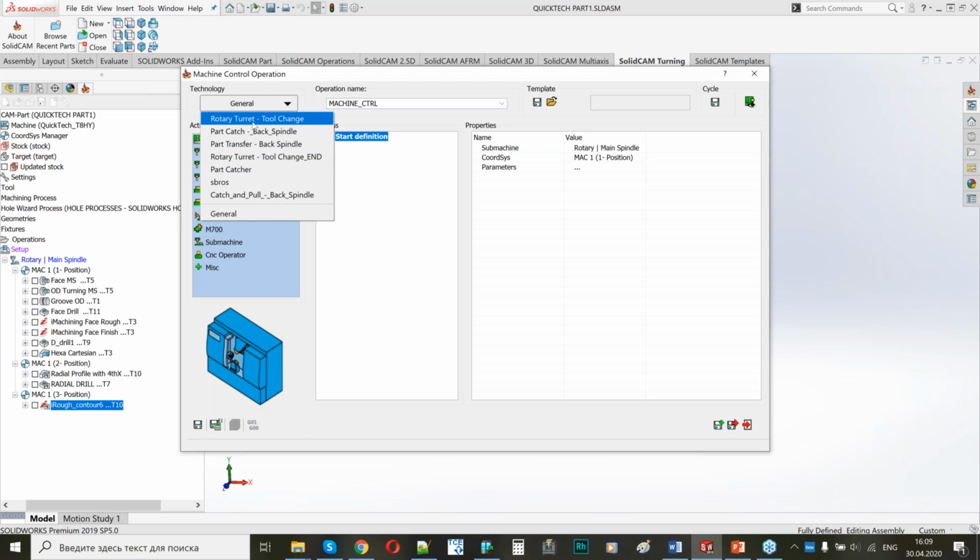It will be connected with the turret. As I said, it's a common routine for this machine and also for machines with turrets. Before you do the cutoff, you should prepare the cutoff tool and position it at a place which is appropriate for the back spindle, to avoid collision with the turret and with the cutoff tool.